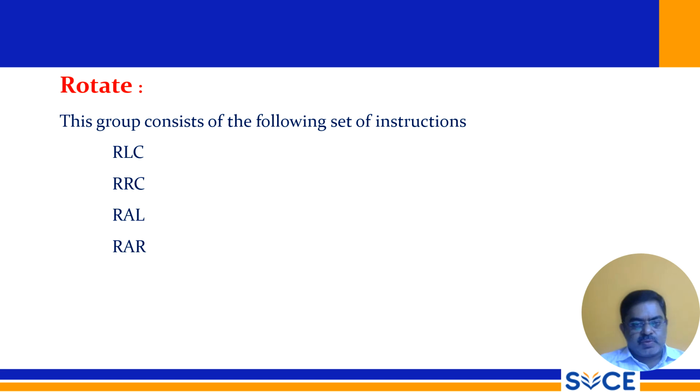Then the rotate group. So rotate: RLC, RRC, RAL, RAR. These are the 4 instructions. RLC, rotate the contents left through carry, and RRC, right through carry, RAL and RAR.